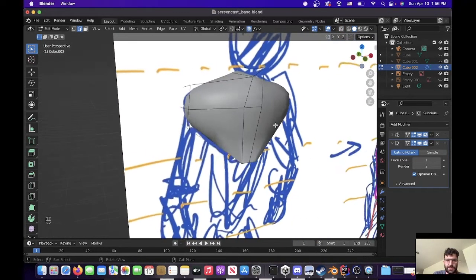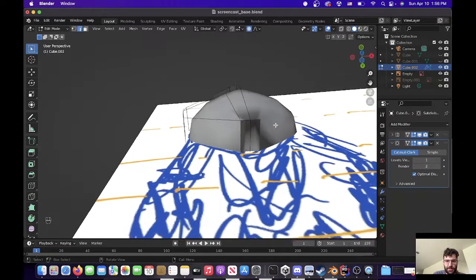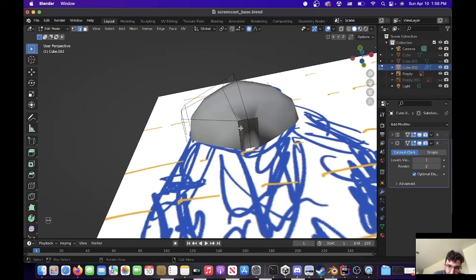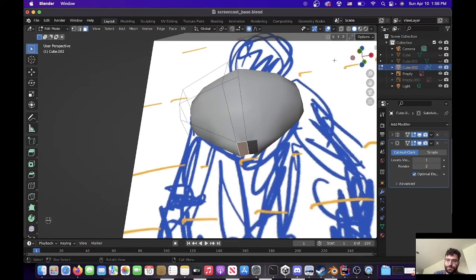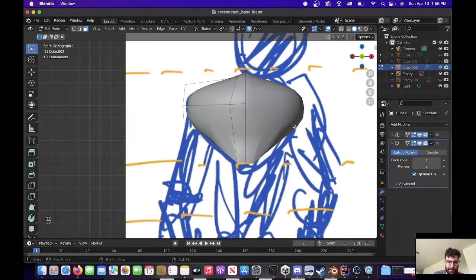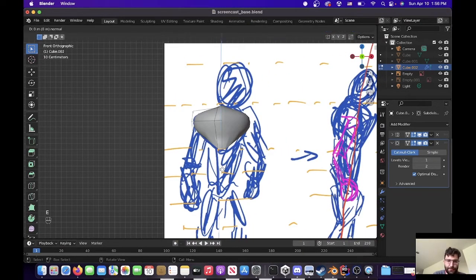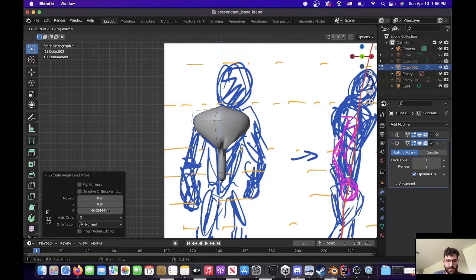All right, so there's our model, and we're gonna use this to our advantage. On the bottom right here, we have a face. This is where the power of extrusion comes in. So hit E, and you can just extrude it downward. Extrude it for as many segments as there are torso. Any time more segments is better than no segments.